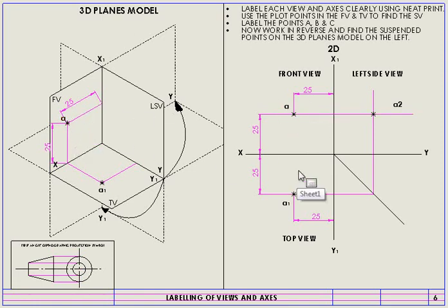Let's look at my top view. In my top view, I've got exactly the same kind of information. Remember that if I want to test whether this is orthographically correct, I'm going to line these 2 lines up, and that will present an orthographic correctness. If those 2 lines did not line up, I would obviously say that we have to redraw my top view and find the proper A1 to be orthographically correct. Alright, the information away from my XY axis tells me that it is 25 millimeters away from the XY axis.